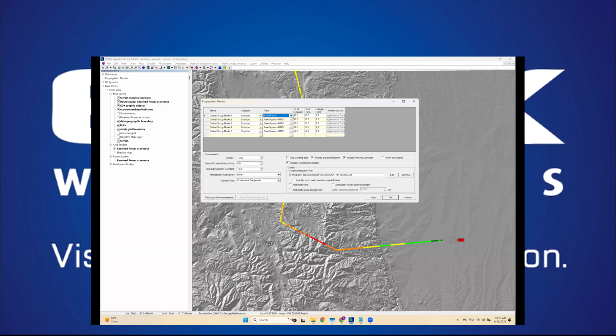So if the aircraft is reasonably close to the ground and you expect propagation conditions to be dominated by the terrain surrounding your terrestrial sites, then one of these path-based propagation models is probably most appropriate. If you have something at extremely high elevation, there is an alternate propagation model, this ITU-R 528, that we'll talk about a little further in the presentation.